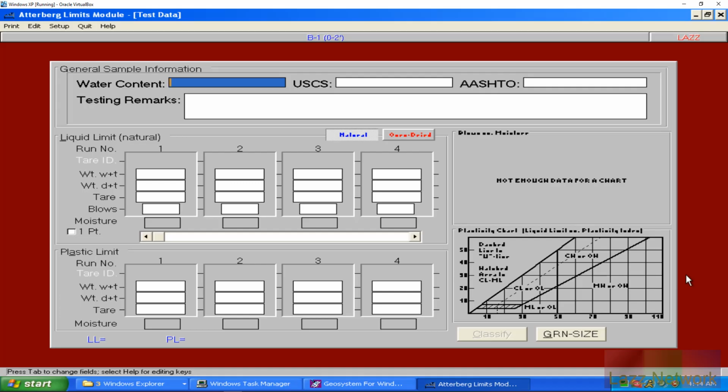But the thing is that the plastic limit of a soil is where you're able to roll the soil down to like a 3 millimeter diameter. So almost like a little log that you would roll down to a 3 millimeter diameter, and you keep doing that until it becomes brittle and falls apart. Because everything here is all based on a moisture content. So before I go any further, let me talk about moisture contents.